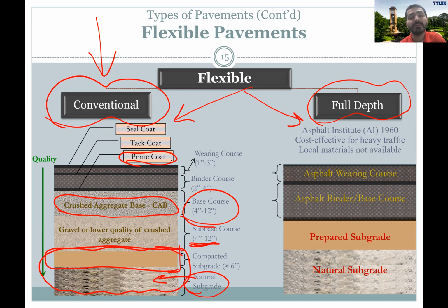I don't like that word. I like asphalt. So the asphalt, or if you are in the UK, they call it bitumen. This is where we mix about 5% by weight of asphalt plus 95% of aggregates, and this is what we use to pave the top layers of that conventional mixture.